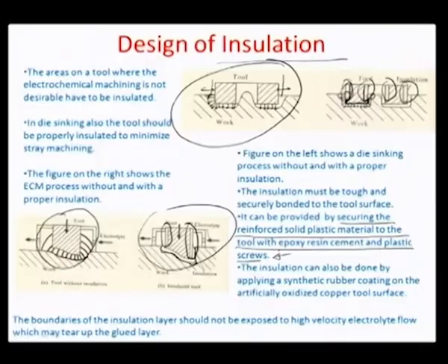A little bit of gap between the insulation and the tool surface would result in, number one, incomplete finishing, because bosses or ridges may form because of that gap on the surface. At the same time, it can also take away the insulation with time, because there is a continuous electrochemical action going on in whatever portion is uninsulated and left over on the tool side. So typically you have to secure the insulation very firmly onto the sides of the tool.